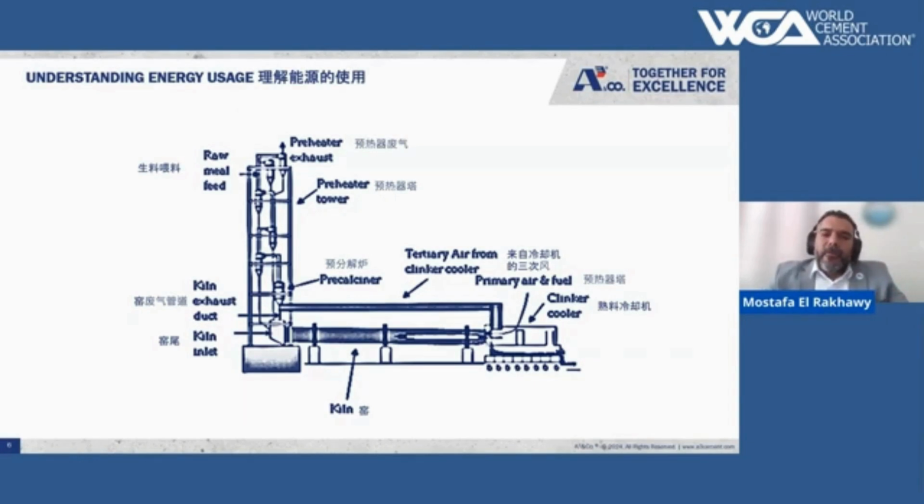Then we come up with what is called the baseline value or thermal reference value, and this should be the designed reference value. If we cannot identify this, or the plant does not have such tools to identify it, it can go back to, for example, its commissioning reference value, the PGT value. After we get this value, we start to audit it in the continuous operation. I will come to how we audit, and this is in the context of thermal power.